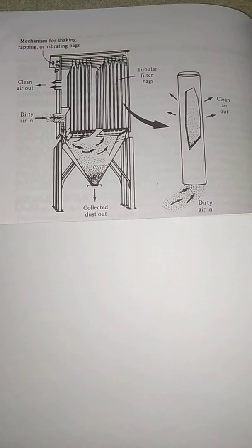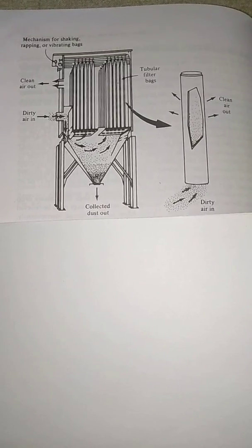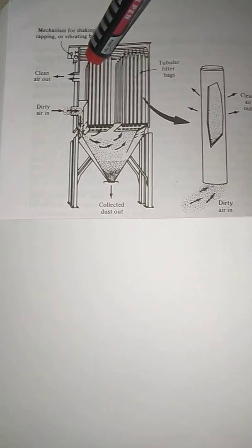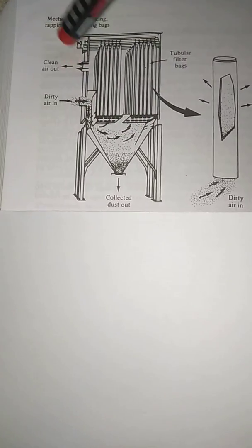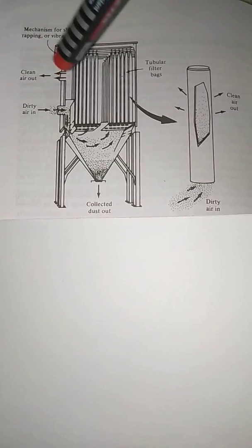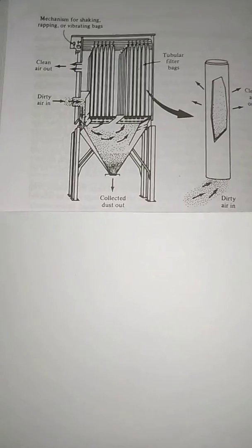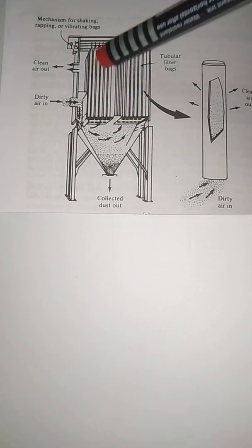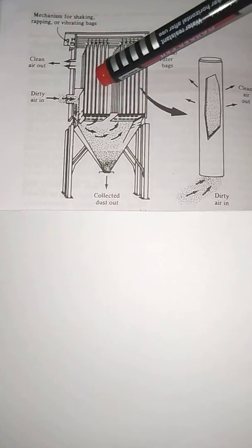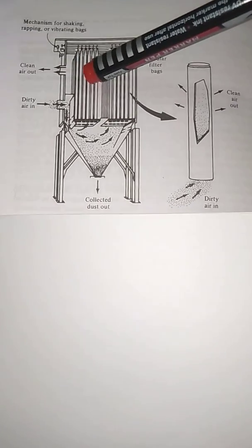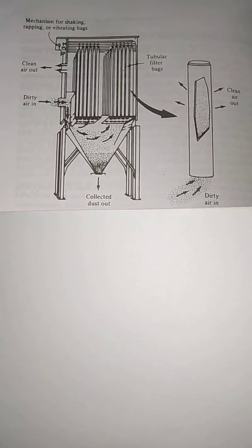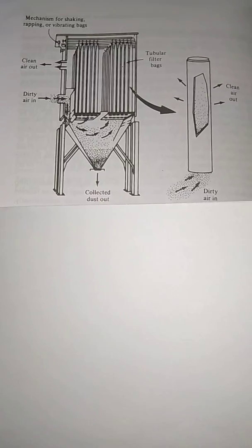Now, maintenance is also going to be required in these filters. If these filters are clogged, they cannot clean the polluted gas, so we require maintenance work. How are we going to maintain it? We are going to remove the suspended particles which have been arrested in the fabric. We are going to clean it by the process of rapping, shaking and vibration, and by reverse airflow.